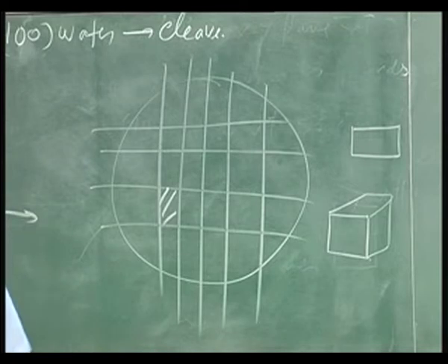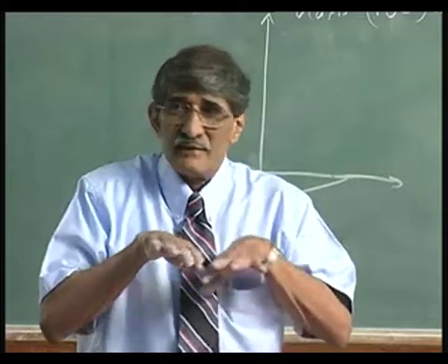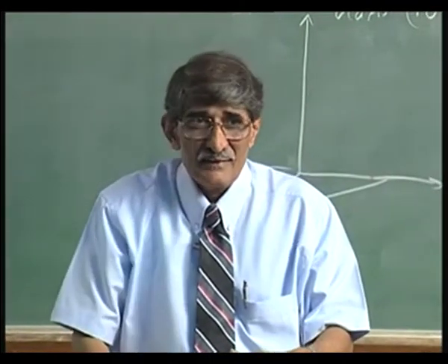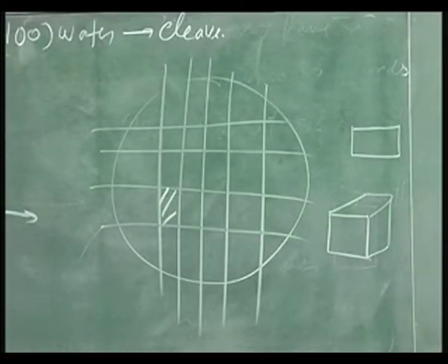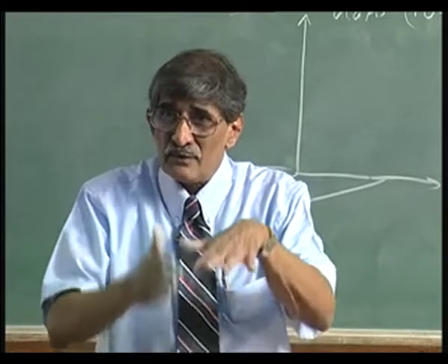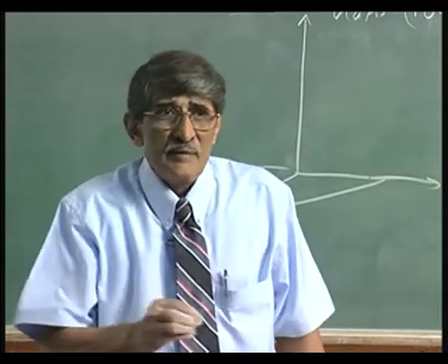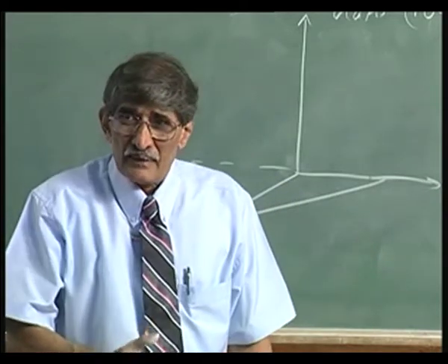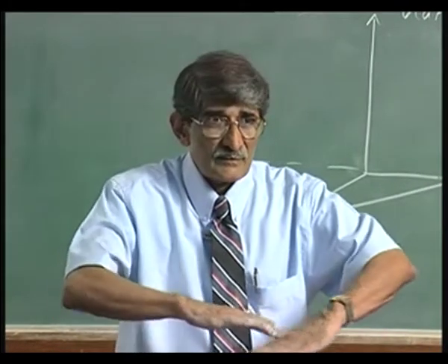But when you go to make a laser, you want the plane where the light is coming out to be polished and vertical. So, when you want to make lasers, this cleavage plane being perpendicular to 1 0 0 helps you. In fact, you can have those surfaces which are shining and which give that laser in that plane. So, for making laser diodes, this property is very useful: the property that the 110 plane is perpendicular to the 100 plane.